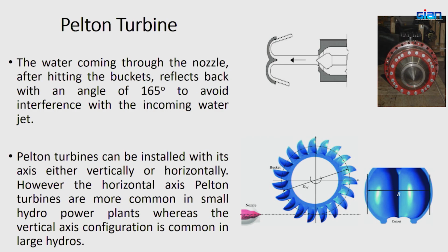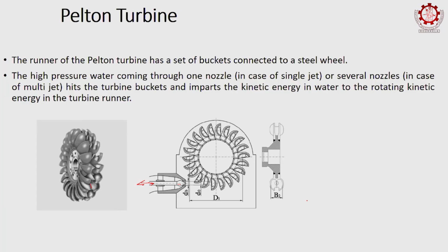The problem with the welding or bolting is fatigue failure. I think you have heard about fatigue failure. When you take a steel wire and bend it a couple of times, it breaks. That is due to fatigue failure. Several times you bend it, it breaks. It is the same way when these buckets are subjected to constant regular stress at the bottom, at the stem here.